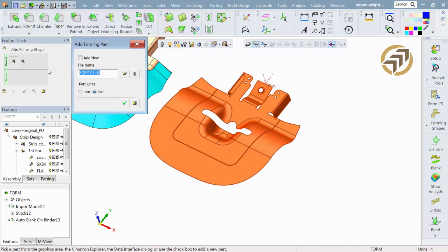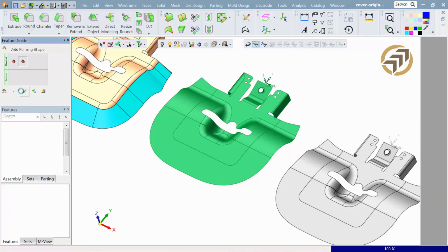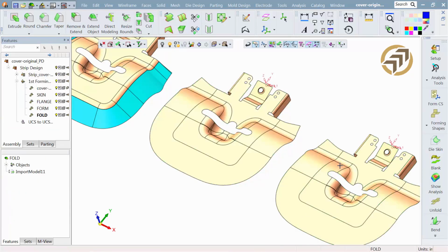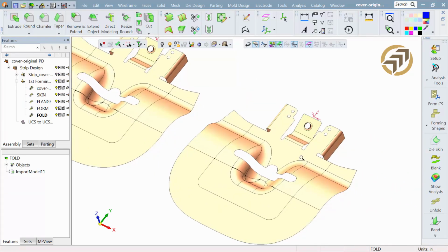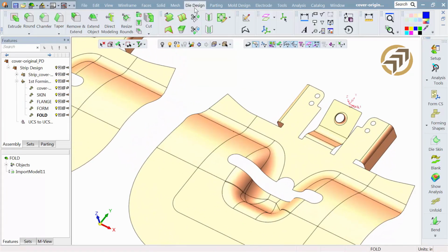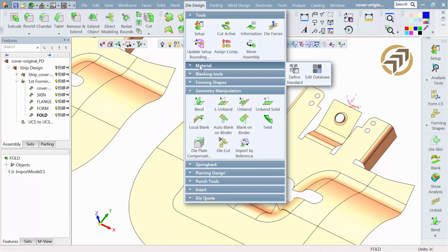All right, with that, let's go a little further here in doing our forming. Let's look at the end now, where we've got those straight linear bends. That's a simple 90-degree bend, so we'll use our unfold function for that.